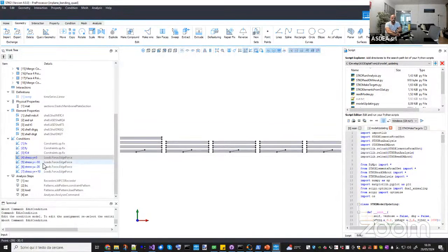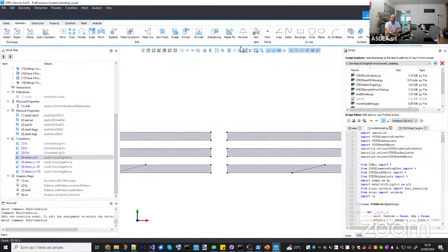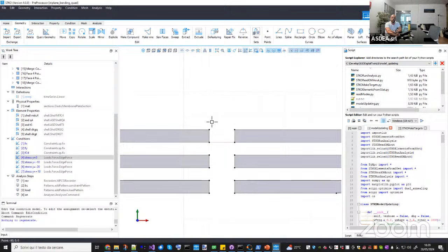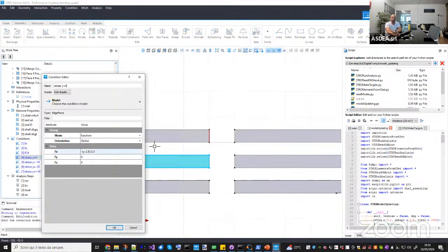So the only reason why I created 4 of them is because, for example, if you take the one here where the basic, okay, so here the grid size is 10, here I'm at 0, this one is 5. So if I want a stress that is -1 on top, +1 on bottom, I take Y, I remove -2.5, which is 1/2 of the thickness, and I divide it by 2.5, okay?